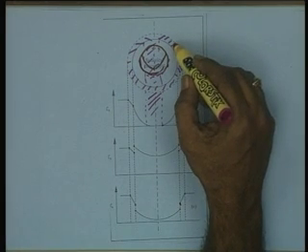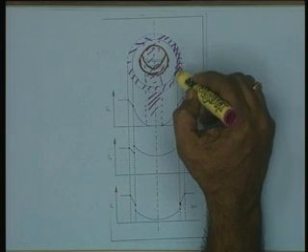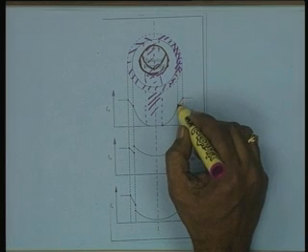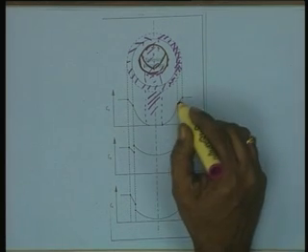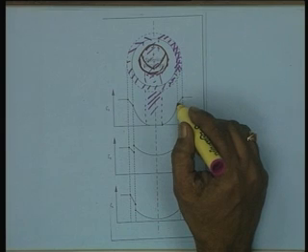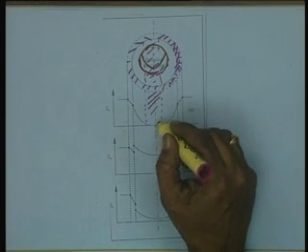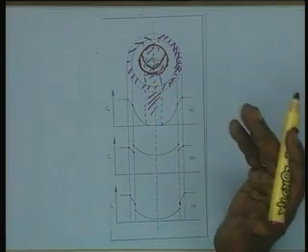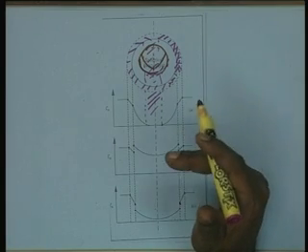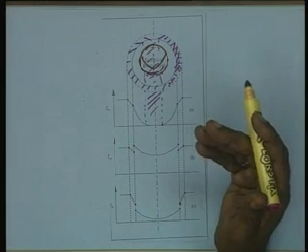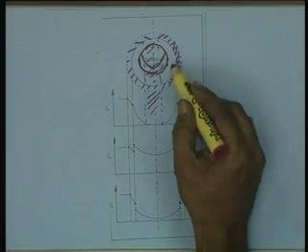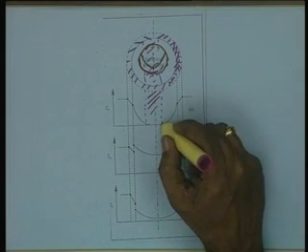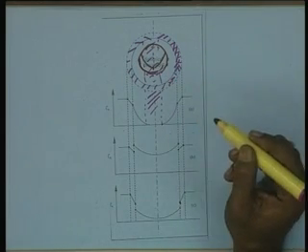If you consider the thin film, then from the bulk there might be a linear substrate gradient across the thin film, and the concentration might drop at the surface, and from the surface to the interior of the particle, that means to the center of the particle, there might be again a gradient as a result of biochemical reaction, because the substrate will be consumed, and as the substrate progresses through the particle depth, the concentration will be dropping down, and there are two possibilities.